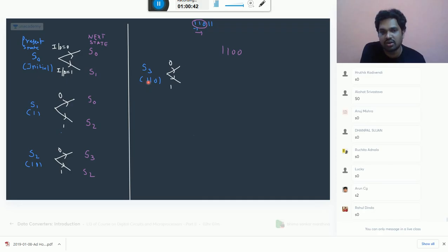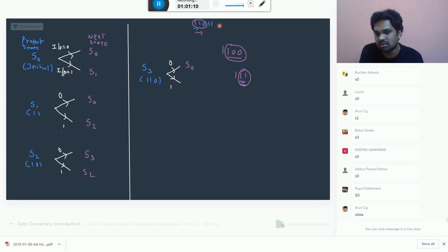Double one double 0 is a failure, so you should go to S0. Earlier triple one may this is part of your sequence. Here you see the last 3 bits. This is not part of your sequence. Here last 2 bits are part of your sequence. After double one zero, zero came, see the last 3 bits, in this 100 is not your sequence. Or last 2 bit or last single bit, you see anything is not part of your sequence. Understand the logic? You should design like that. Okay, don't design it to S3. Next, you are a designer now.